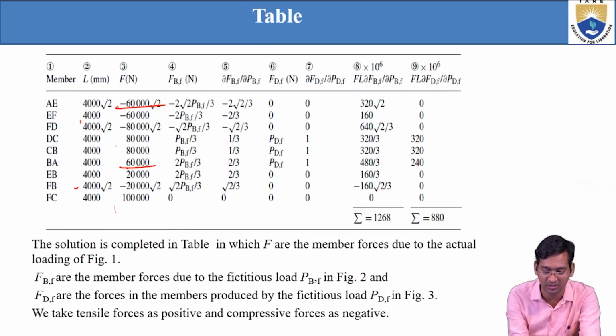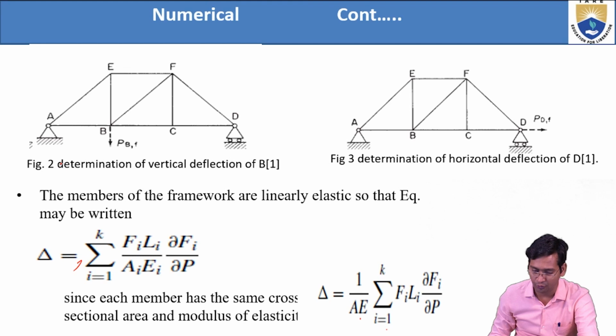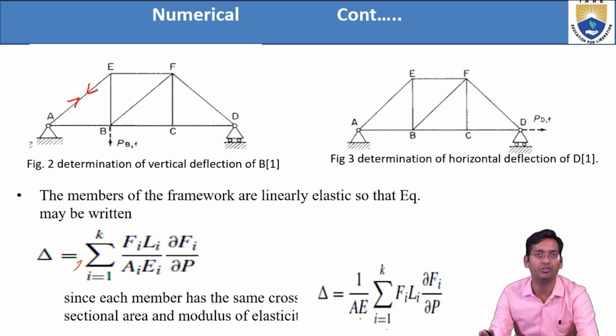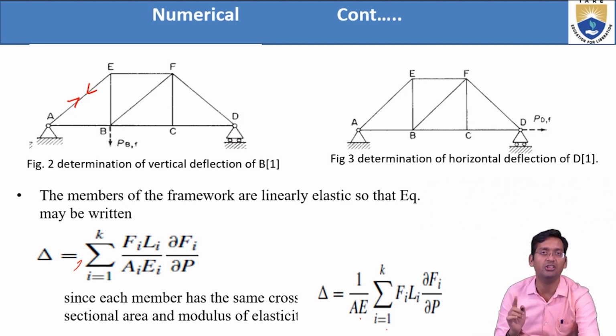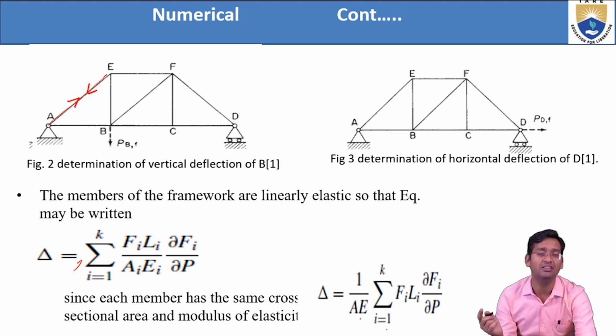Because we are finding FAB and here you can see in the table it's given as BA, right? Once we apply the forces, if compression is there, that member will have compression only, not elongation, because both are not possible simultaneously. If it's getting extended or elongated, then only elongation, and if it's compression, then compression. Like FAB, if you take that as compression, then EA will also have compression only. If AB is expansion, then BA will also be expansion only.